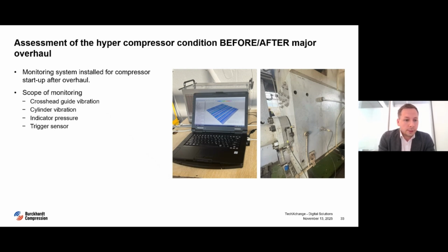And to facilitate this, a decision was taken to bring a temporary monitoring system with all capabilities like vibration measurements on the crosshead guides, on a cylinder, in a time domain, indicator pressure, and these signals have been synchronized with a crank angle position by a trigger sensor connected. So this was the scope of the system.